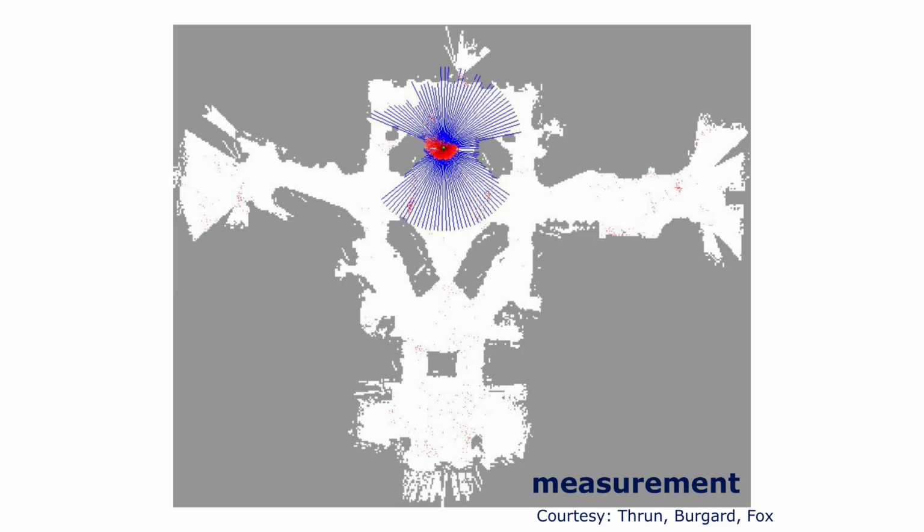The robot takes yet another measurement. This measurement helps the filter correct the increased uncertainty from the motion step. Weights are updated again. Particles that closely match the measurement become darker, representing higher probability. The filter is now zeroing in on the robot's true pose. Here, we perform another resampling step. Unlikely particles die out, and the distribution becomes concentrated around the most likely robot pose.